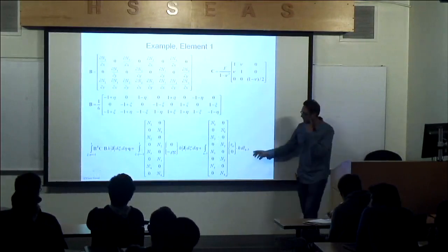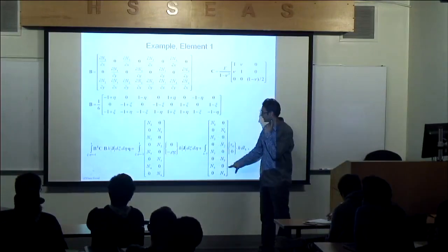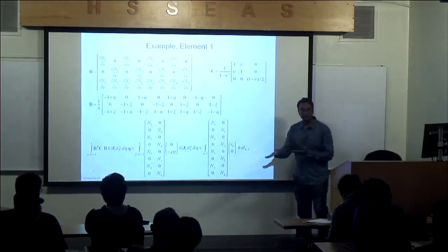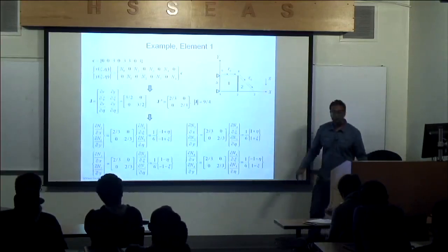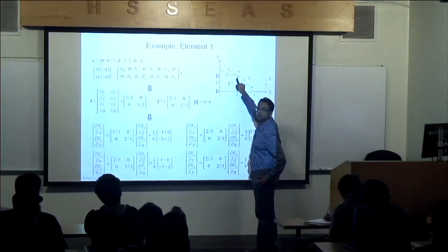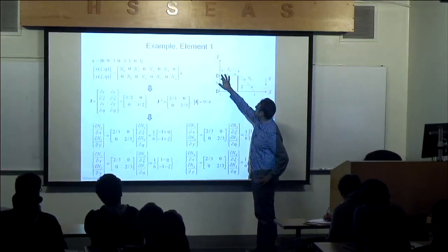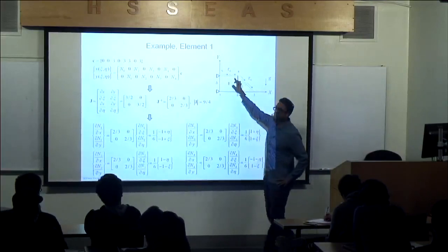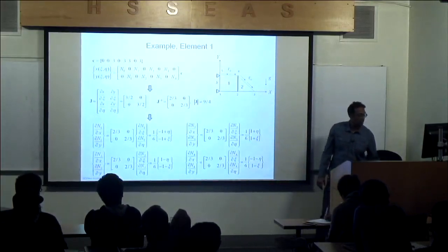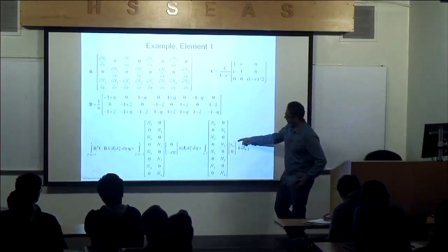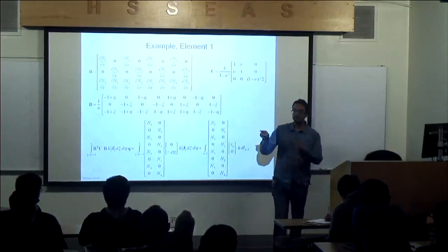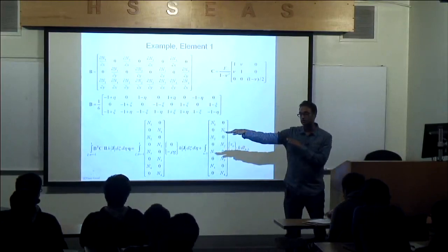I'm going to ignore this a little bit longer, but we can cover it a little bit now. So if you remember, I'm applying a surface traction. And I'm applying surface traction on edge 4, 5. You agree on element 2, 1? Yeah? So that's a surface integral that I had to calculate. If you remember, that was N transpose times traction, bold. So traction bold, you saw that in the previous picture, T bold only had components along the x direction.